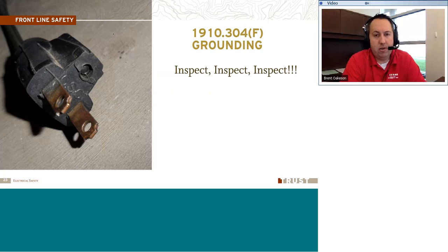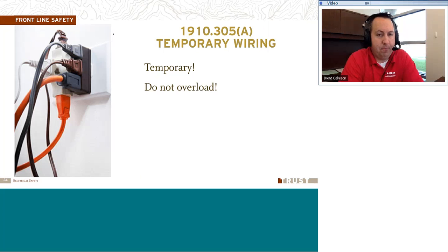So check your cords. It happens a lot on extension cords and the ends of tools, where they have the 3 prongs with the grounding prong missing. That happens a lot. Check that out. Make sure that the grounding is there. Inspect all of your equipment. Make sure that there's nothing open or any hazards or problems there with the electrical.